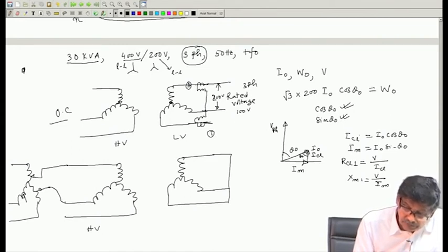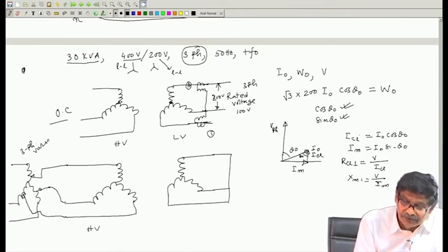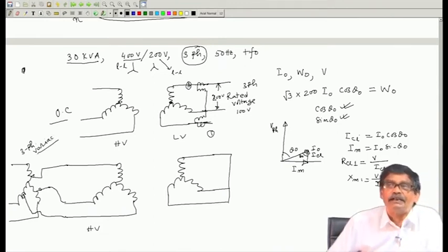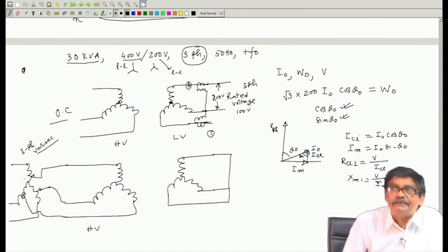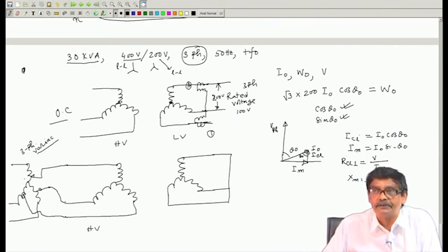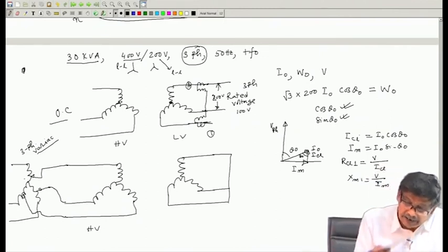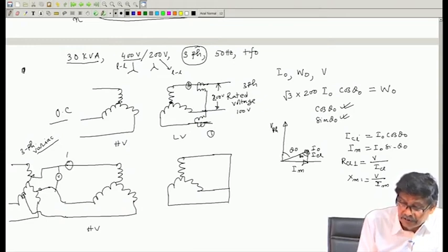It is not an auto transformer, I should call it a variac, 3-phase variac, because you must be knowing the difference between a variac and an auto transformer. Auto transformer means in this winding you are using different sections of wire, you get an advantage. Anyway, so you measure the voltmeter reading here, VSC, you record the current, you connect 2 wattmeters.